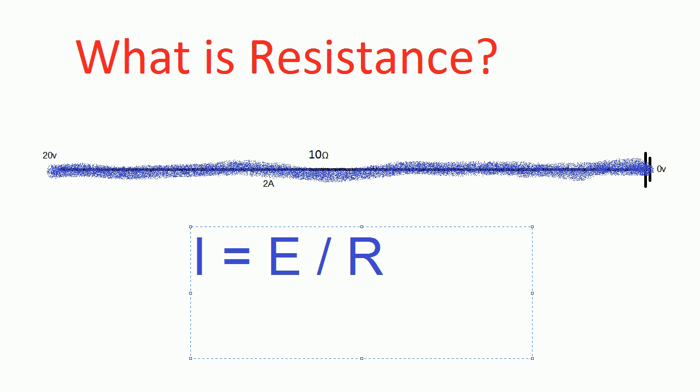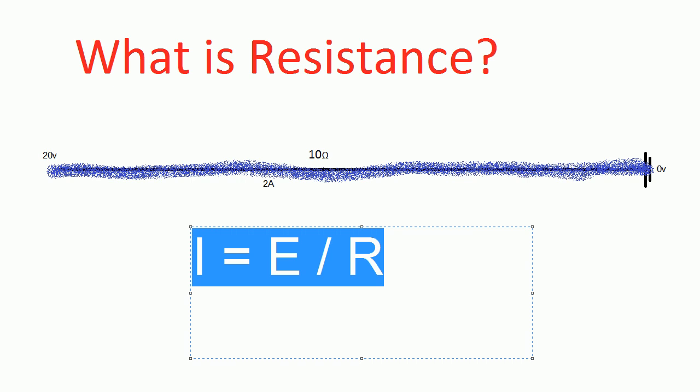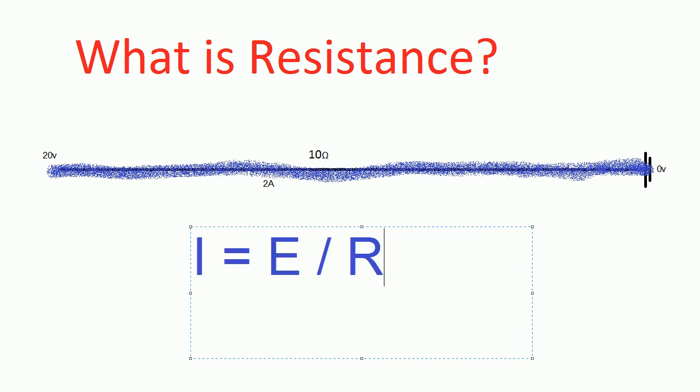That's our electrical pressure, and if you need more information on electrical pressure / voltage, then check my video on that. And it has the same relationship, whereas V is the unit, E is the symbol for the actual force, and the same with omega and R. Omega represents the ohm, and R is the actual resistance. So what this equation states is that the amount of current flowing is equal to the voltage divided by the resistance.